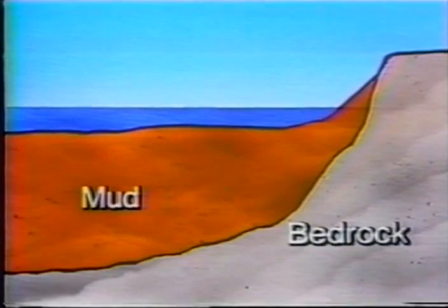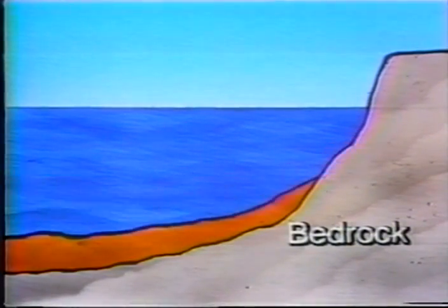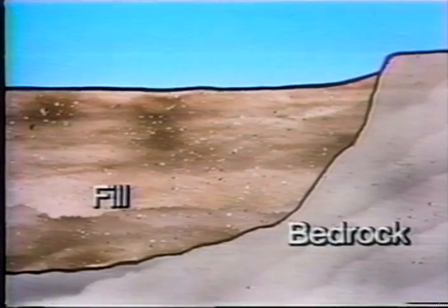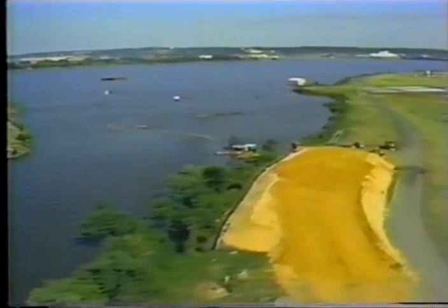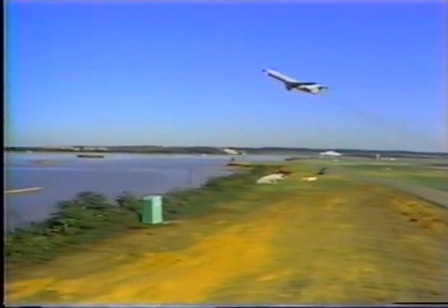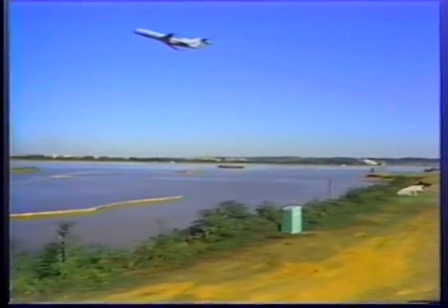The alternative would have been to excavate large quantities of soft, unsuitable material and replace it with more substantial fill. This would have been much more costly and environmentally unpopular. It would also have taken about 3 years, whereas it took less than 100 days to provide the airport with a geotextile reinforced embankment for the runway extension.